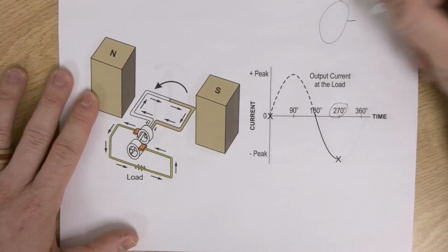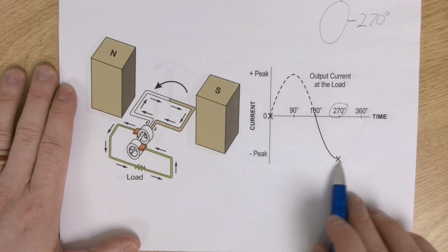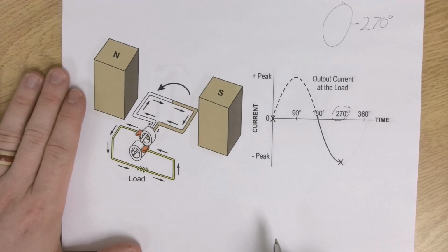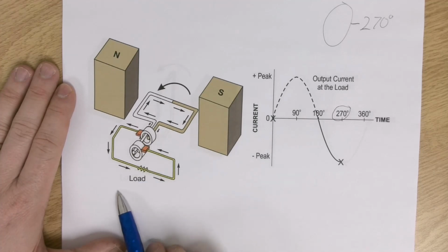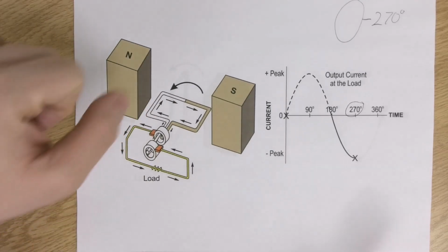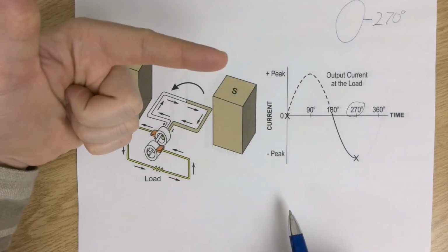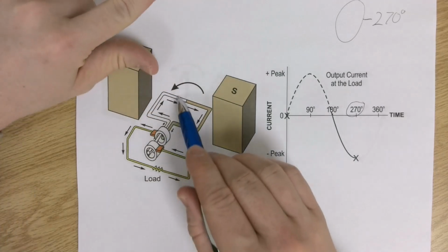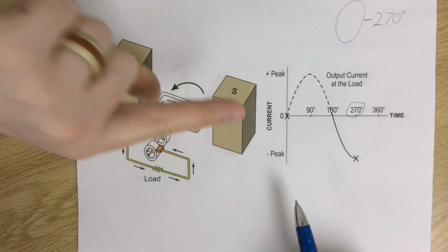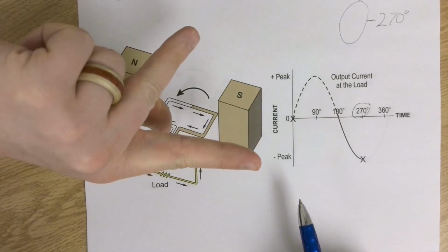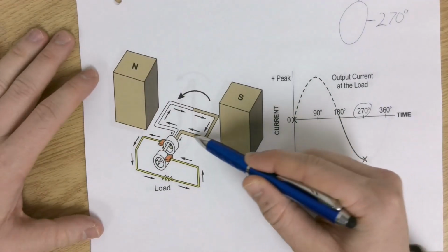So once again, if we drew our circle, this would be 270. But the reason it's down here at our negative peak is quite simply because of which slip ring is touching which brush. So in our armature, using our left-hand rule for generators, or Fleming's left-hand rule, whatever you want to call it, same thing's happening. Because our finger is going from north to south, and if I'm looking at this white part of the armature, the direction of force of the conductor is going down, which means my current is going that way. And then the opposite is true over here. The direction of force of my conductor is coming up out of the page, which means current is coming down this way.